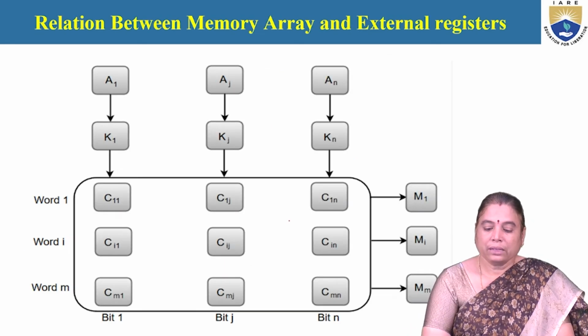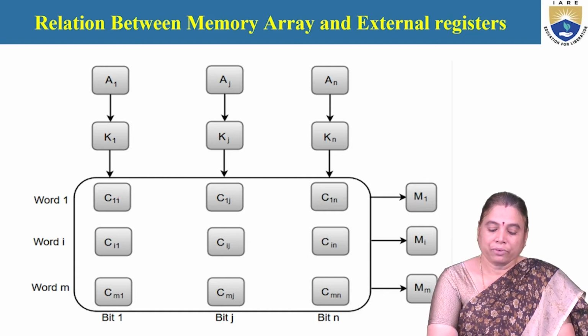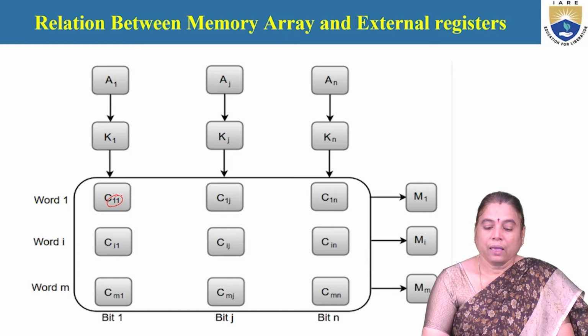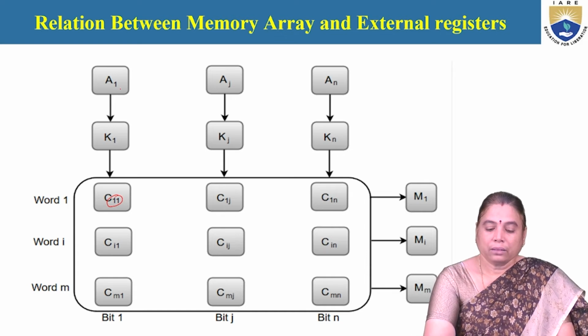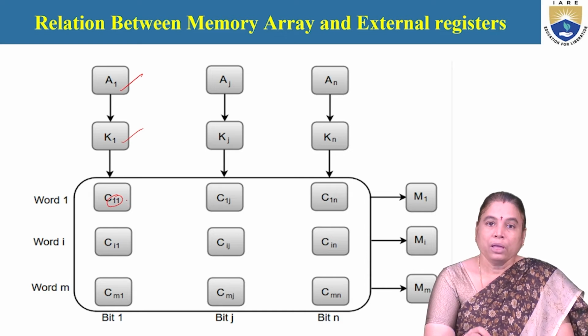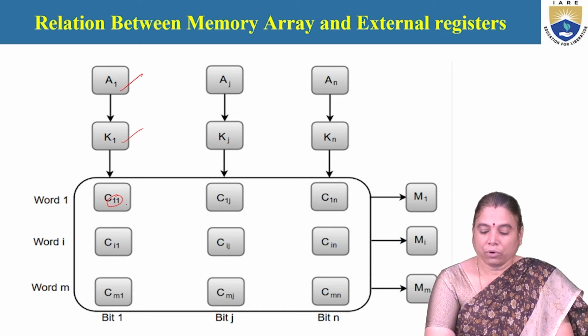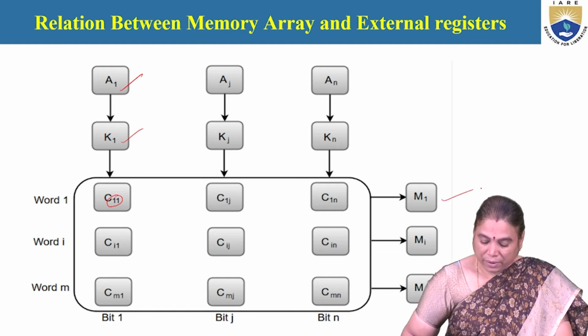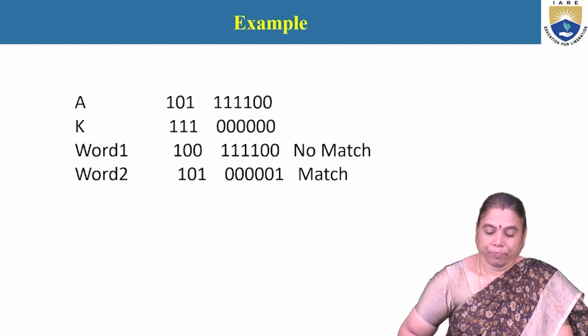So here within the associative memory, the cells or the words are matched with two indexes, the row and column sizes, and for each bit, the search word argument register and the mask value has to be compared with the word value. If they are equal with the word, then the corresponding match bit can be represented as high.